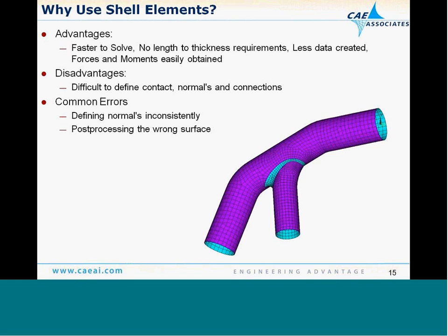One of the things you've got to be careful about with modeling shells is to make sure you have consistent normals, such that when I put a pressure load, the pressure will act consistently over all faces. Mechanical APDL, for example, when you plot your model with the types active, is going to show the inner and outer surfaces with colors. So you can clearly indicate the region where I need to reverse my normals to get consistent results from the lighting perspective, and it also helps in the post-processing.